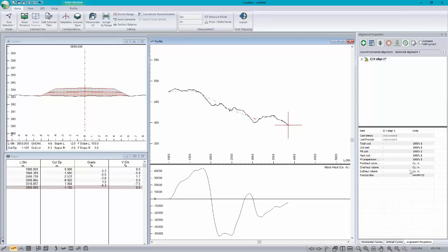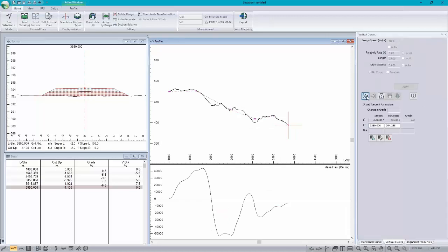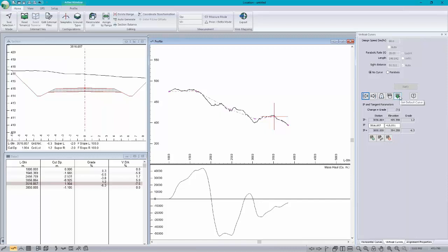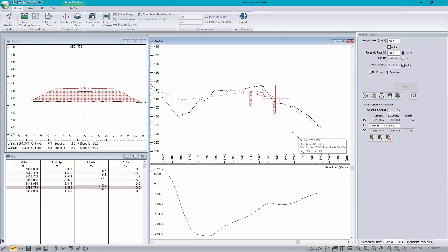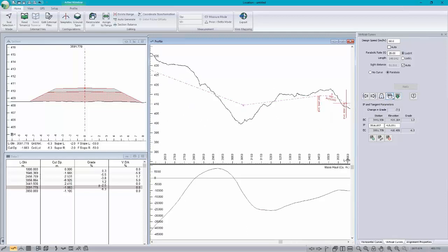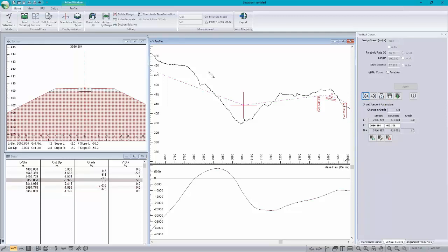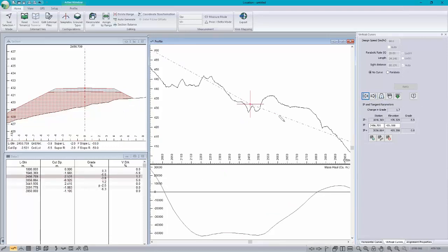And I can throw in curves too. Let's look at vertical curves. I'll put the default vertical curve on there. That curve came from my template table. Once you've created a set of vertical curves that you like, you can save it. You can say that's my default curve. Click on that button there, and the next time you save your template table, that gets put in there. Or if you like, whenever you open a template table, you get default curve parameters.